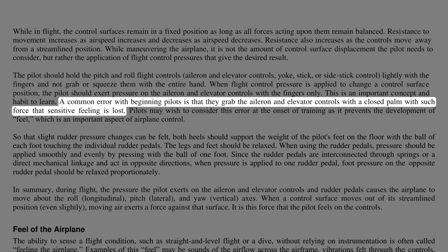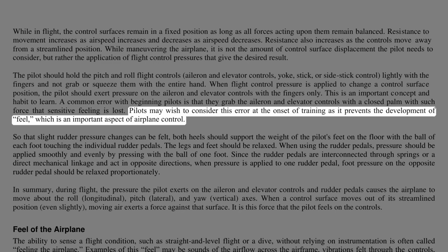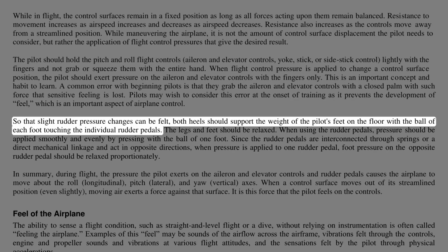A common error with beginning pilots is that they grab the aileron and elevator controls with a closed palm with such force that sensitive feeling is lost. Pilots may wish to consider this error at the onset of training as it prevents the development of feel, which is an important aspect of airplane control, so that slight rudder pressure changes can be felt.